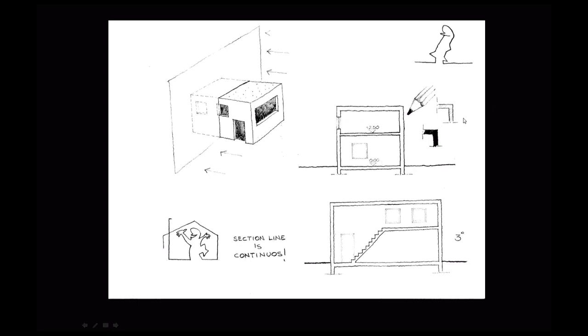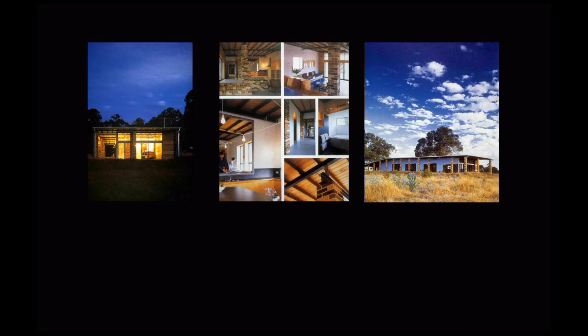You can see here there's multiple ways of actually shading a section, or where the section cut takes place. You can have a nice bold white space surrounded by a thicker line weight, or you can actually color it, or you can actually diagonally hatch it, however you choose to. Just note that wherever a section cuts through a building, it always exists as a continuous line. Doesn't matter what color you actually use.